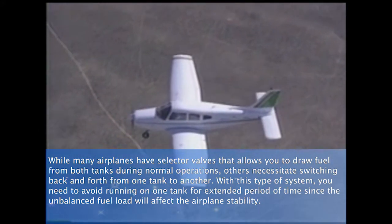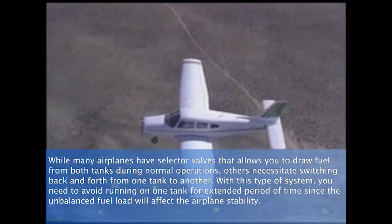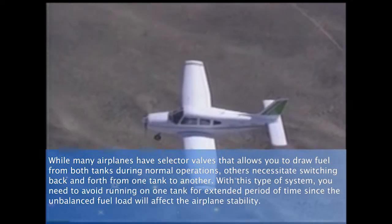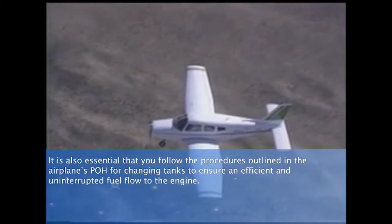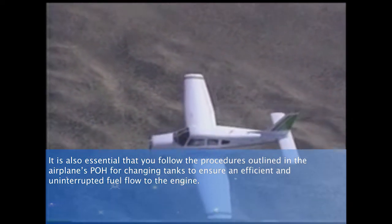With this type of system, you need to avoid running on only one tank for an extended period of time, since the unbalanced fuel load will affect the airplane's stability. It's also essential that you follow the procedures outlined in the airplane's POH for changing tanks to ensure an efficient and uninterrupted fuel flow to the engine.